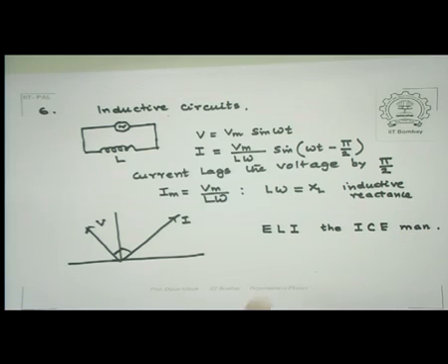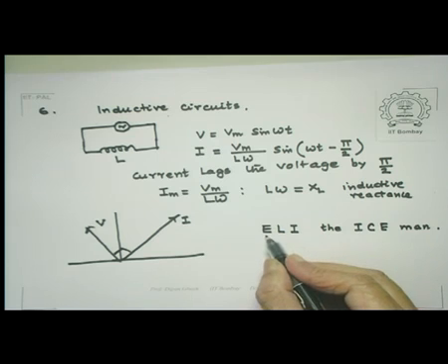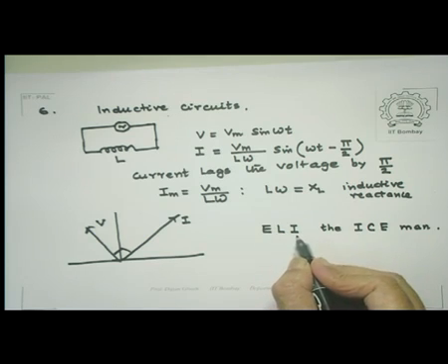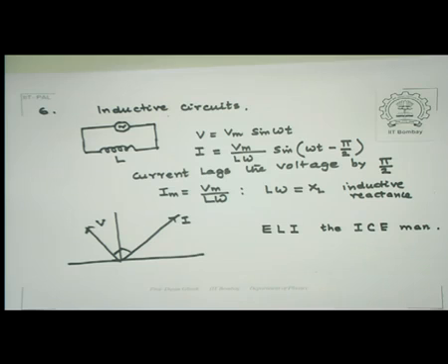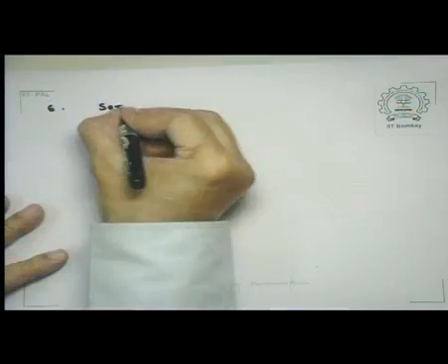Standing for that, for an L in the circuit, the EMF comes before the current does, that is, EMF leads the current, which is the same statement as current lags the voltage. And for a C in the circuit, it is the current which comes before the EMF, that is, current leads the voltage. Having done these individual elements, we discussed a series LCR circuit.